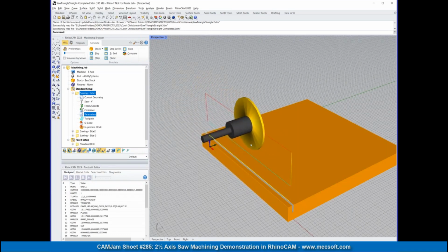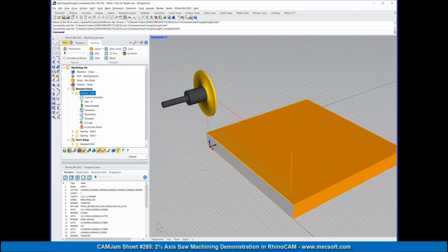This one is out of the box, so you don't need to do anything in terms of index machining, because if you look at our toolpath editor, the rotary axis is actually rotated by 180 degrees to machine this. The system automatically figures out the rotation of your C axis.